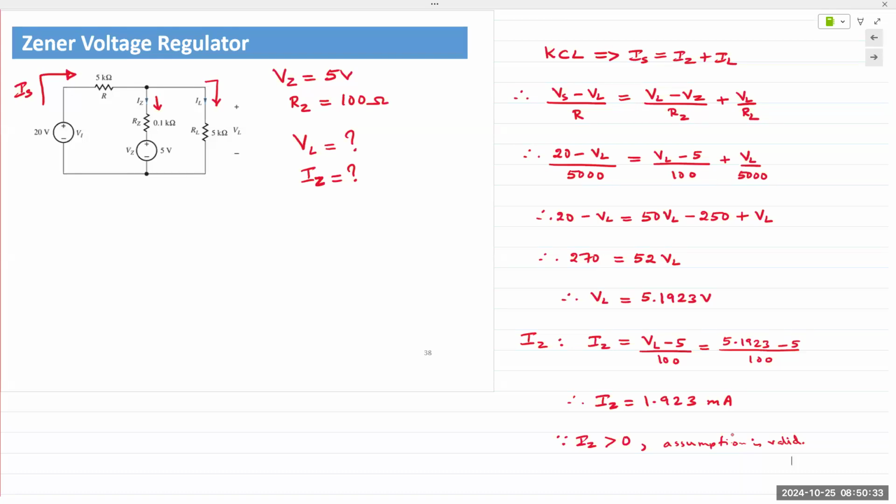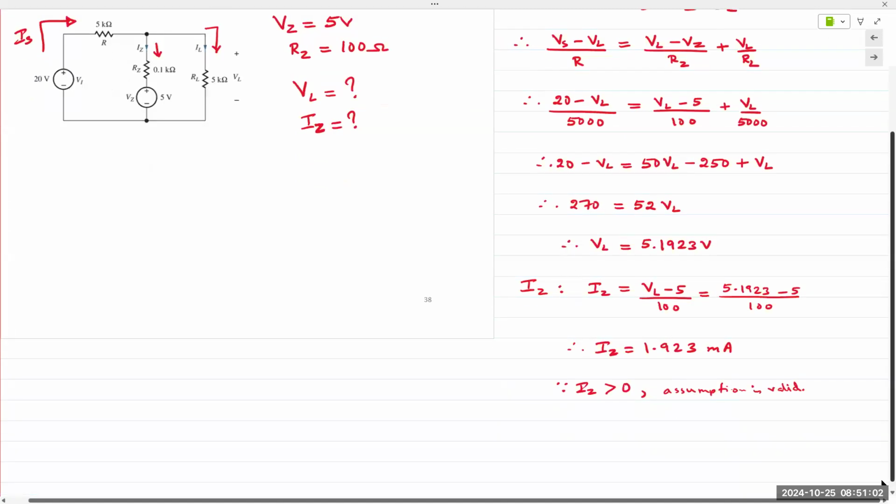And if the line voltage changes, then how does my output voltage change? That is described by a parameter known as line regulation. Both parameters are expressed as a ratio of voltages: the change of output voltage VL as a function of the input voltage, or as a function of the change in the load resistor. Let me write those down right here on this side.